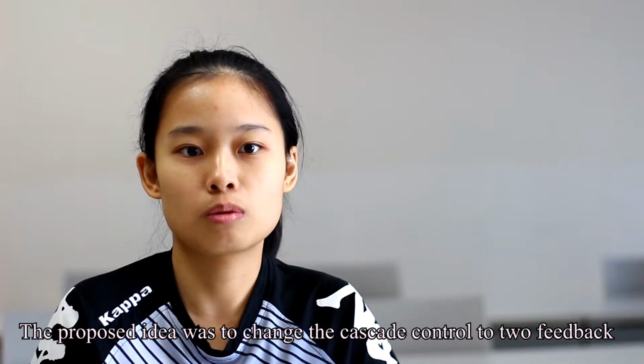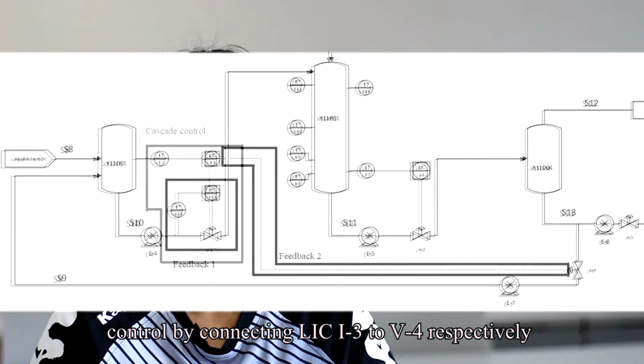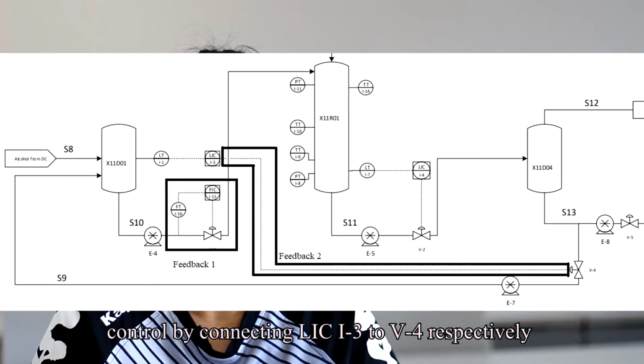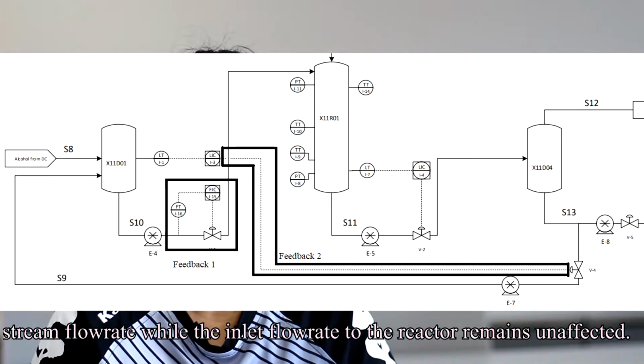The proposed idea was to change the cascade control to two feedback control by connecting the level indicator controller to the fourth valve respectively. That way, the level can be controlled by just adjusting the recycle stream flow rate, while the inlet flow rate to the reactor remains unaffected.